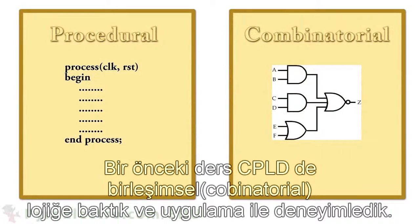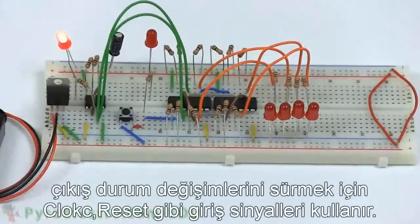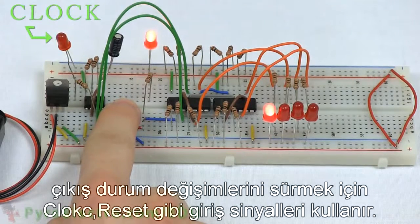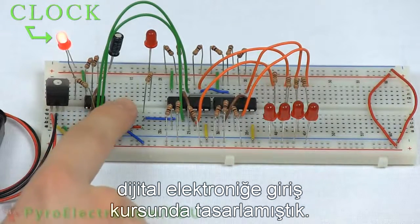In the previous lesson, we took a look and experimented with implementing combinatorial logic in a CPLD. But in this lesson, we're going to take a look at the other type of logic used in CPLDs and FPGAs called procedural logic. Procedural logic uses input signals like a clock or reset to drive state changes in outputs, similar to the clock in this shift register that we designed in the Introduction to Digital Electronics course.